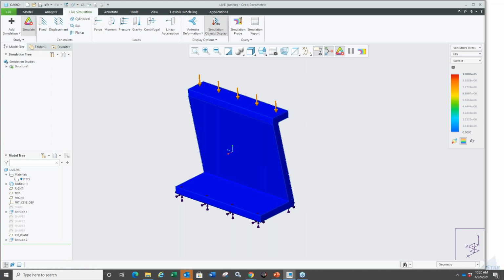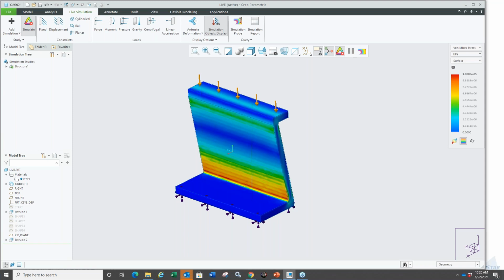This is when the Ansys Discovery technology is working behind the scenes. Ansys came out about three or four years ago with a product called Ansys Discovery Live. Many of you may have heard about that. So that's the technology working behind the scenes here. That's the engine that's making this work. So immediately I get, okay, there's my von Mises stress. Maybe I would like to know it in a specific unit system, right?